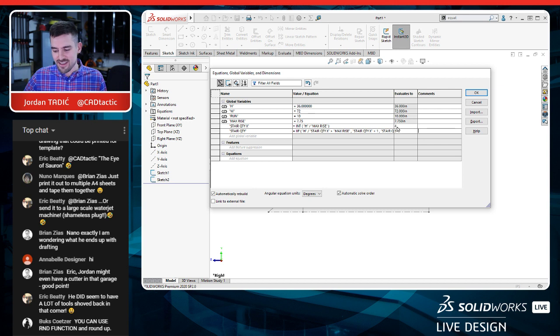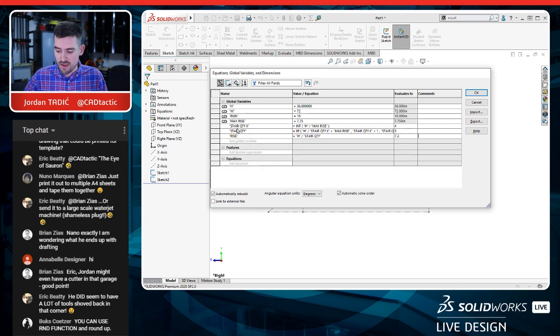It does the math, finds out that 4 is not enough steps, adds one more, and tells us that the final stair quantity should be 5, which means our rise should be the height divided by, once again, the actual stair quantity, the corrected stair quantity, which is 7.2. And 7.2 is, of course, less than 7.75, so we are good to go.